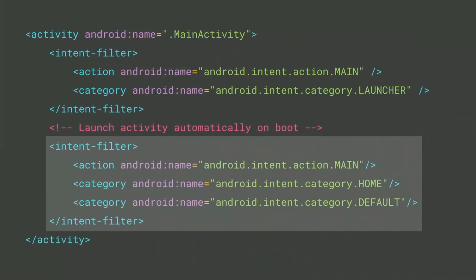Android Things even uses activities to launch your primary application as part of the boot process. We do this using the home intent, which is the same intent that's used to trigger the app launcher on an Android mobile device. This intent starts your app automatically on boot, and specifically the activity inside of that application. In addition, if that application crashes or terminates for any reason, Android is going to restart that application automatically. So this becomes the main entry point into your application that is automatically managed by the Android Things platform.